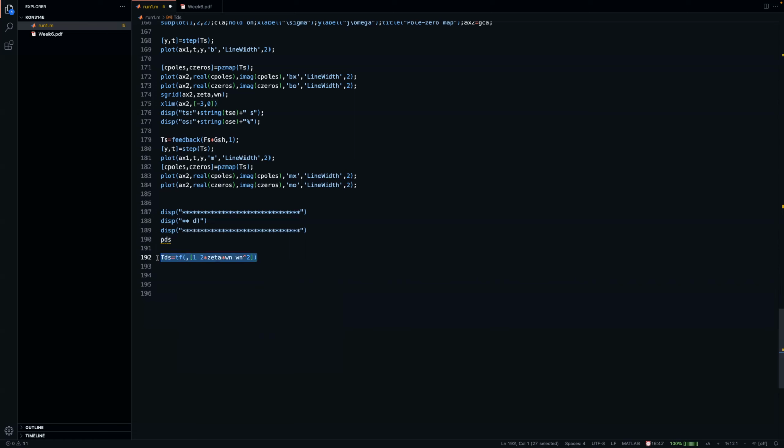So therefore, if we are trying to state a desired transfer function, since we're looking at problems with reference tracking, it seems like we should add some numerator that would end up in perfect reference tracking. And if you think about the final value theorem and the fact that we are looking for step responses, it should immediately pop up that the numerator should match basically the constant term here, so that s equals 0 will get rid of these terms. Then omega n squared divided by omega n squared should give us gain 1, which corresponds to y divided by r equals 1 in steady state, so that y is tending to r.